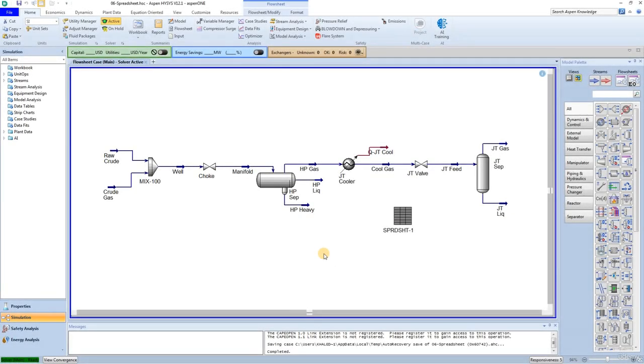Now to our final task, run a case study. The case study allows you to monitor the steady-state response of key process variables to other changes in your process. It contains built-in reporting tools to easily present your results in tabular or graphical format. Click the Case Studies button.